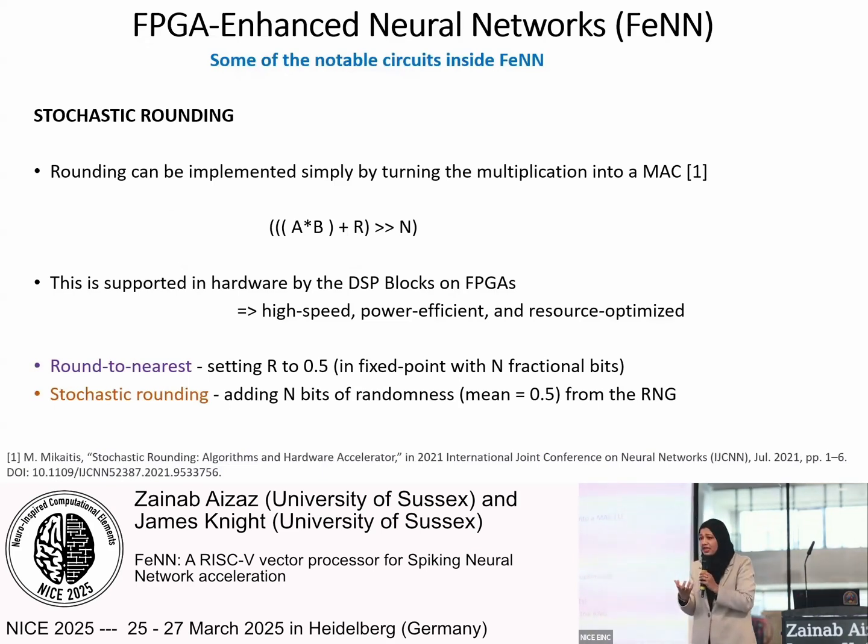Why do we use that shift? A into B, 16 into 16, 2 operands are multiplied, and the output is 32 bits. Randomness is added to it, and now we get an output. Why do we shift it by N equal to 16? Because we want the output to fit into the register file again. We did not increase the size of the register file. Instead, we made it a little more inaccurate by shifting it, because we want a compact circuit.